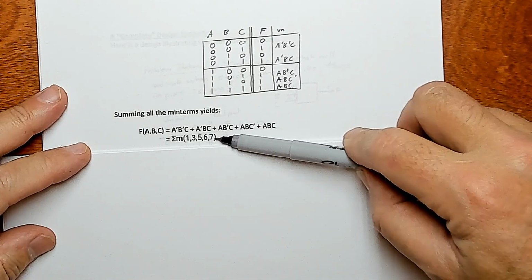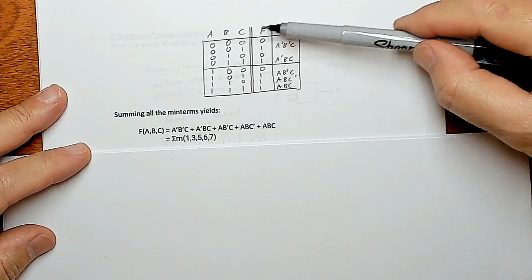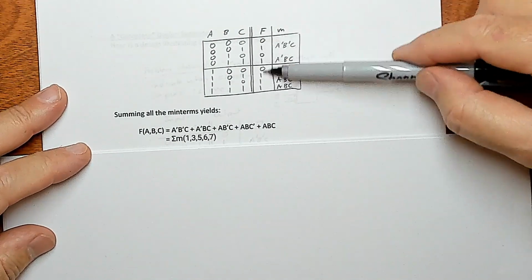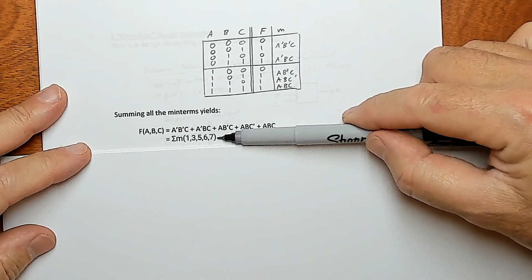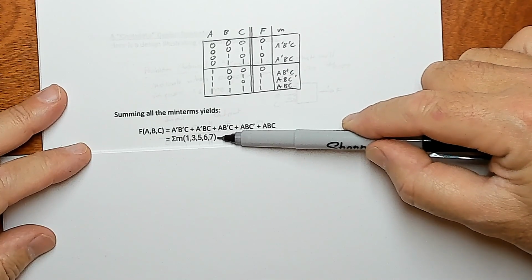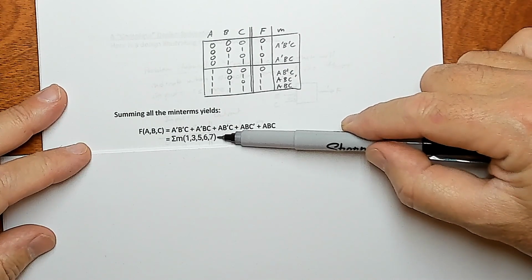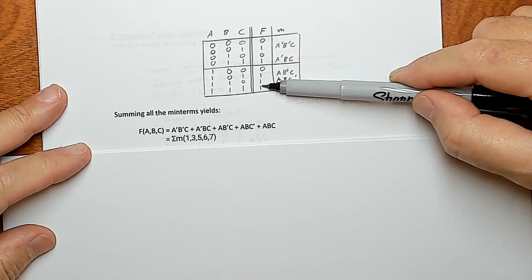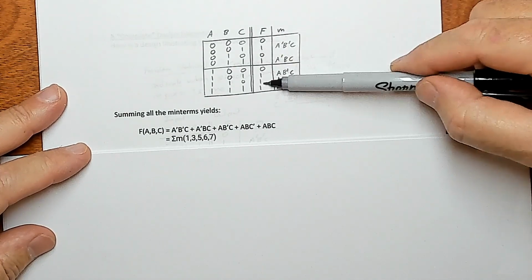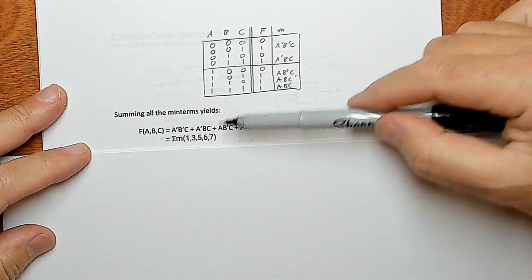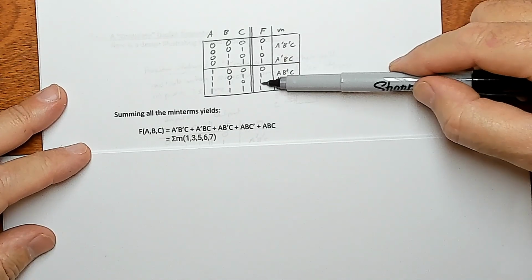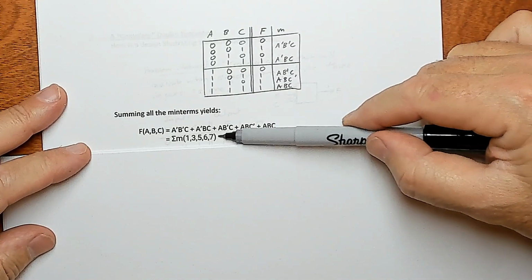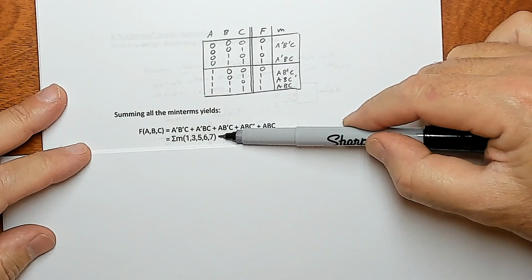And it could also be defined, originally, by the F output column that your boss gave you. He really could have just given you this. That's all this minterm notation really does: it basically specifies the truth table. It specifies the output column. It doesn't tell you the gates that'll make it. It just tells you what the values need to be. It's really the starting point for the truth table.